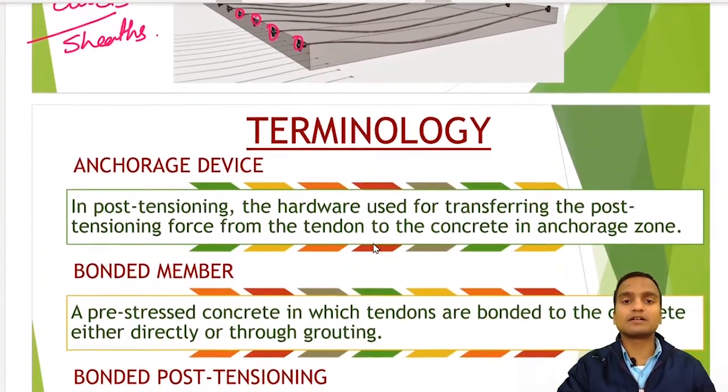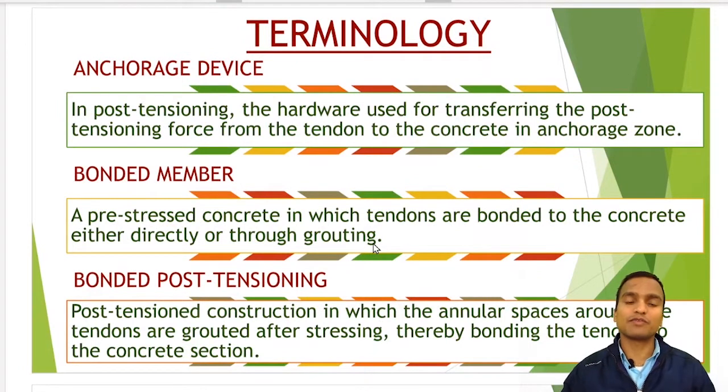Now let us discuss all the terms that come very often in the discussions of prestressed concrete. Here we start with letter A, and first of all we are discussing anchorage devices. Anchorage devices are mostly used in post-tensioning, because post-tensioning is done after the hardening of concrete, and through those ducts we pass the tendons and then we tighten or stretch the tendons with the help of this hardware, the anchorage devices.